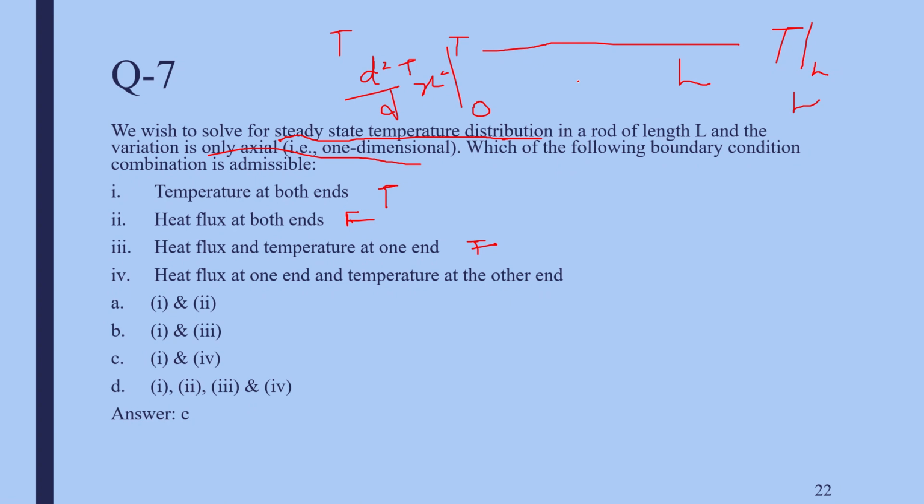So actually there are various boundary condition types. We can use derivative boundary conditions, or we can have constant value boundary conditions. For example, we have temperature values at both the ends, like temperature can be 293 Kelvin here, and 323 Kelvin here, or something like that. And here heat flux at both the ends, d square T by dx square value is given.